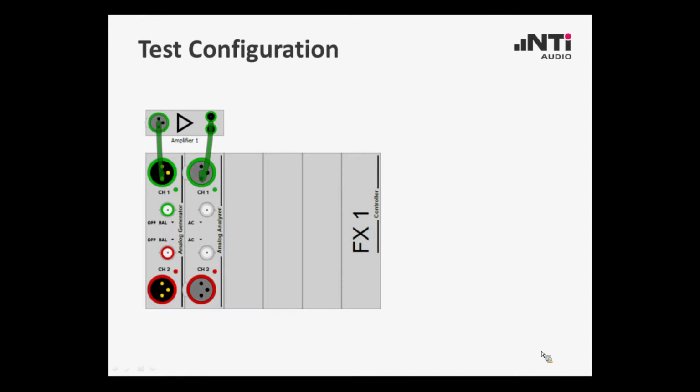So in practice, it looks like that. We have our Flexus analyzer. We connect it to our amplifier. This feedback line is basically required to measure, for instance, the gain of the amplifier, or of course also to measure the voltage across the load here. And the load in our case is 4 ohm in our practical presentation.